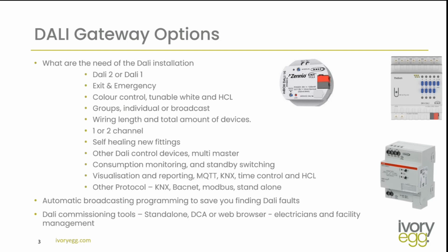The other big consideration, which I'm going to touch on a bit here, I think is underutilized a lot, and that is the automatic broadcast programming. So we have a lot of DALI gateways that are coming out nowadays that are actually broadcast channels. And this just makes things so much simpler. If you're a regular DALI programmer, regardless if it's KNX or not, you'll understand that a lot of your program time and money is put into programming a DALI network and addressing it and grouping it.